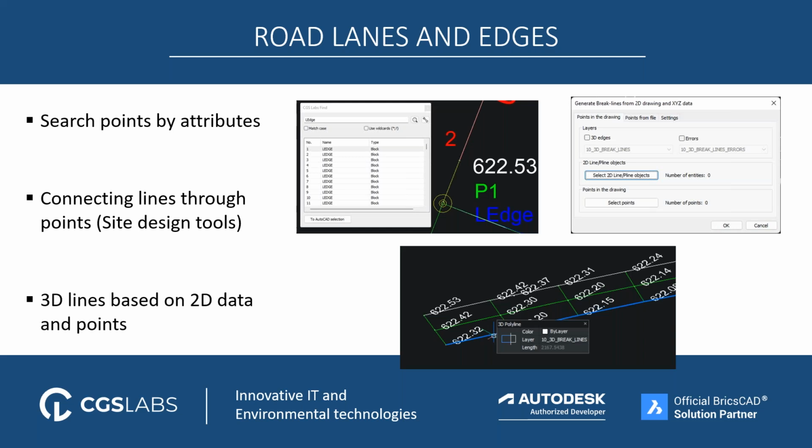Now that we have the cross sections and axis, we can move on and make road lanes or edges. Same thing here, we can use the point attributes to connect all the points with the lines. We can use different tools here. For example, we have some tools in site design to work with polylines. And also we can make 3D lines based on 2D data and elevation information. So let's check this.